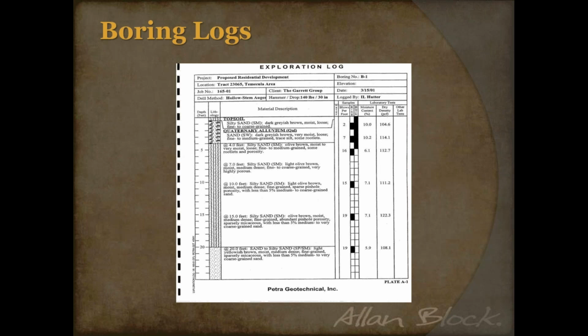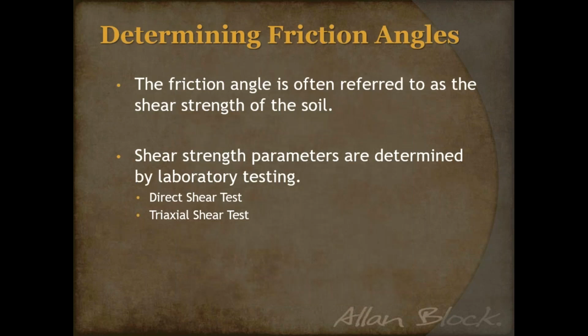unless that's being under like the other lab reports. So like I said, to really get the values that we need, unit weight is important, but then the shear strength is even more important. And that's done through some type of shear testing. There are two different ones that I'm looking at here. You got the direct or the triaxial shear testing, and really the difference is night and day, to be perfectly honest. Direct shear testing, it's simpler, it's faster. You can do that a little bit within the budget. Triaxial is a little bit more involved, but generally most people agree that it gives you better results.